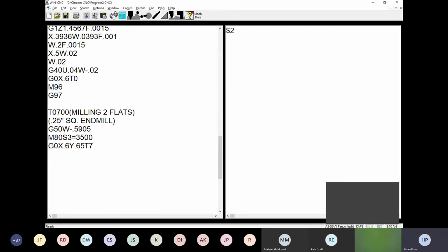That means I'm going to shift the Z0 to the center of the live tooling, which right here is the end mill. So one more thing is right here. If we shift it to the center of the end mill, then we still have to make up the number in order to compensate for the side mill width.